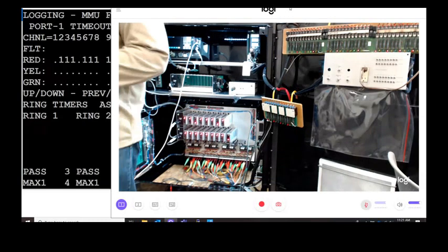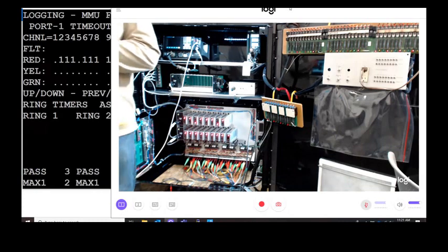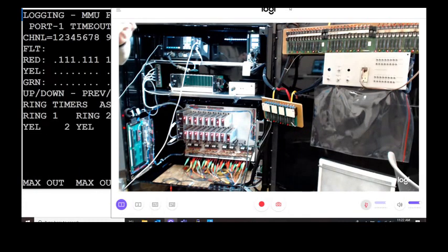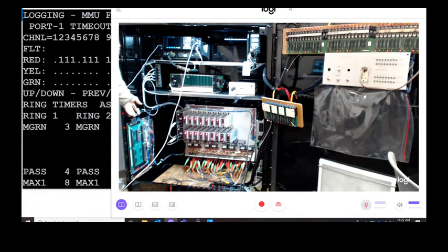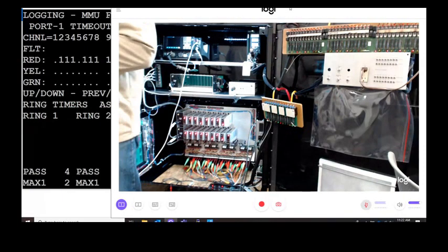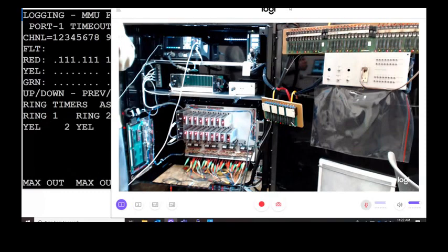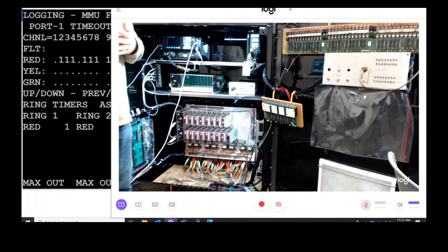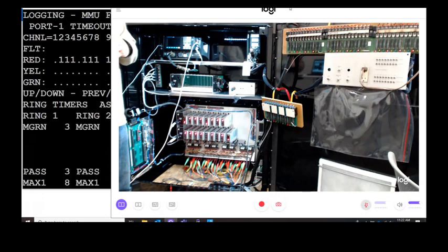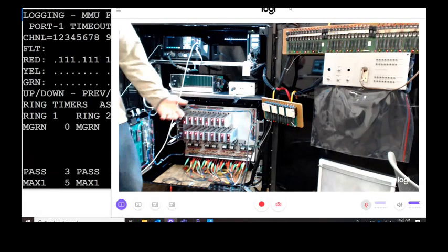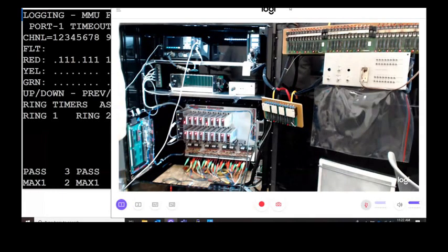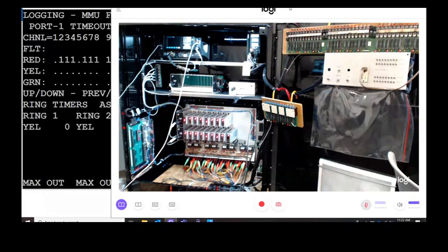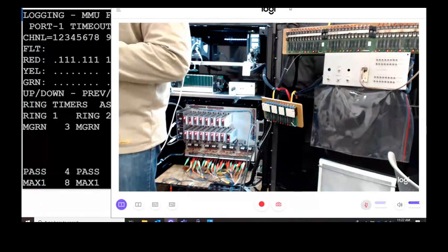So through suppression and better grounding practices, we've tried to eliminate that. The influx of using video detection has eliminated that because we took all the loops and loop buildings out of the ground. So that's diminished it quite a bit, but there's still a lot out there. And then when we shift over to ATC cabinets, in the next 5 years or whatever that's going to take place, there's even more electronics in the cabinet. So it's something that we just have to do the best to deal with, and just try to protect our equipment the best we can, basically.